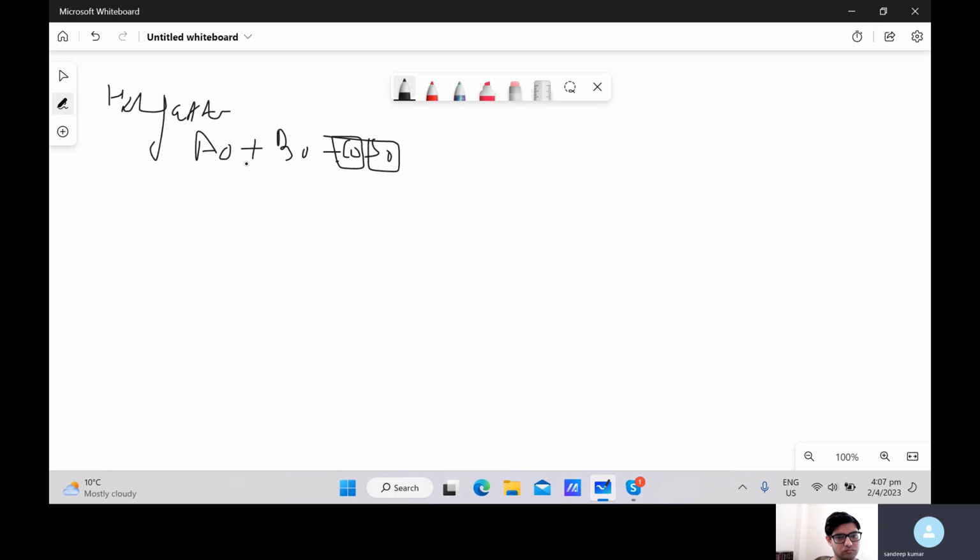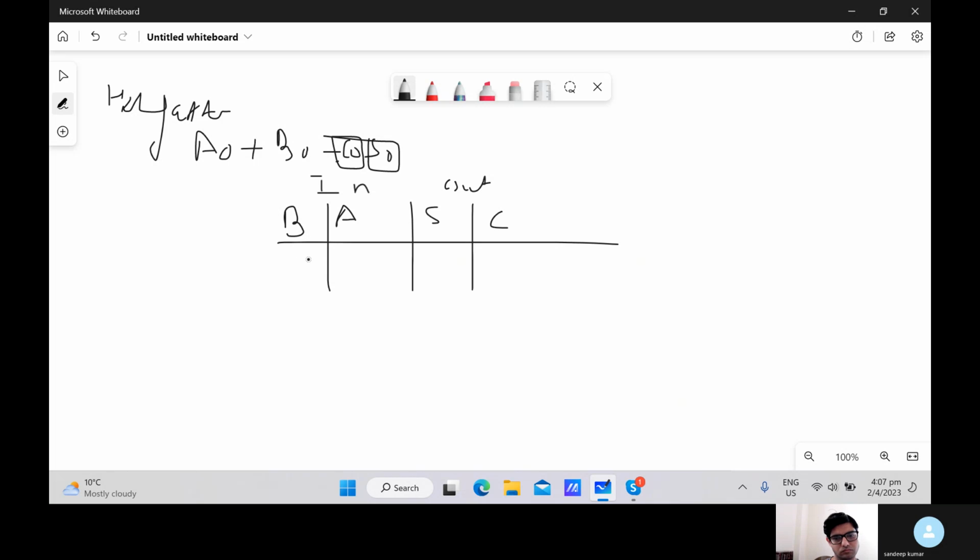So basically, 0 we will not say, we say A plus B in half adder, one bit, A plus B, C and S, okay, carry and sum. Right. Okay. So let's say A and B and generates sum and then carry. And these two are input, these two are output. So all possible combinations: 0, 0, 0, 1, 1, 0, 1, 1.